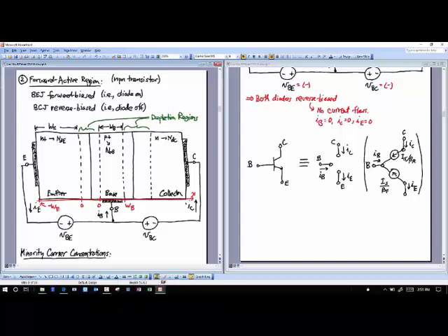Great. That could have been a question I put on the exam as one of those short answers. Right? So that's the kind of physics question you might expect. So yes, P side is negative here. I have negative charge at that depletion region. Then on the N-type side, of course, I'm going to have positive. Why is it negative? It's because to create that depletion region, I push holes away. I pushed away positive charge. On the N-type part, I pushed away negative charge. So this is going to end up being positive. Positive static charge. This is now creating a field, right? So my electric field generated by this is in that direction.